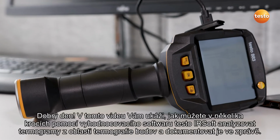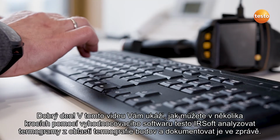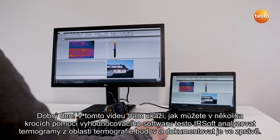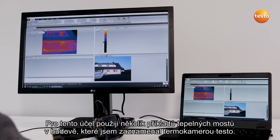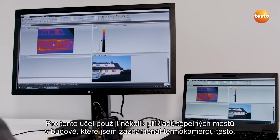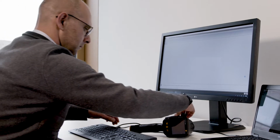Hello. In this video, I'm going to show you how, in just a few steps, you can use the analysis software Testo IRsoft to analyze thermal images from the field of building thermography and document them in a report. For this purpose, I'm going to use a few example images of thermal weak spots in a building, which I've recorded using a Testo thermal imager.